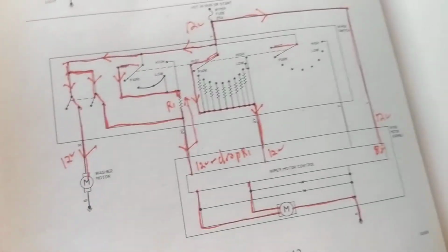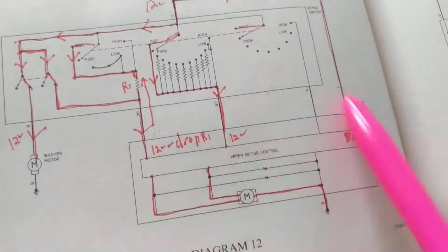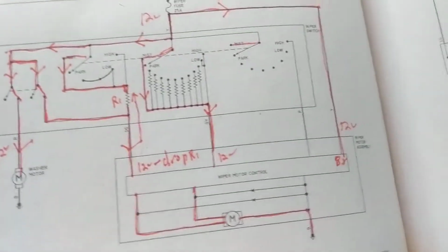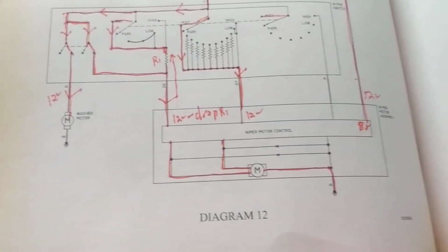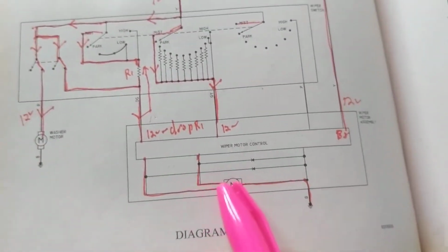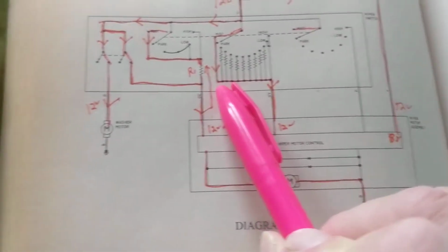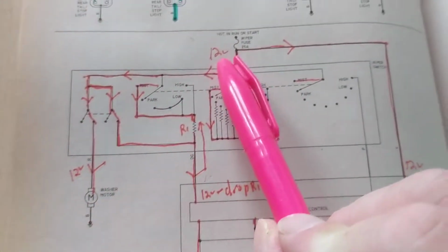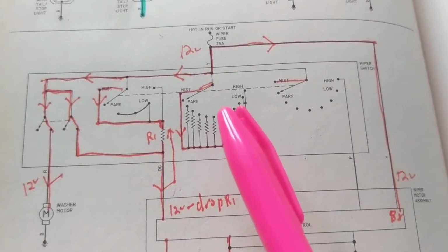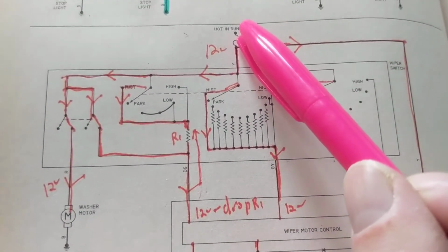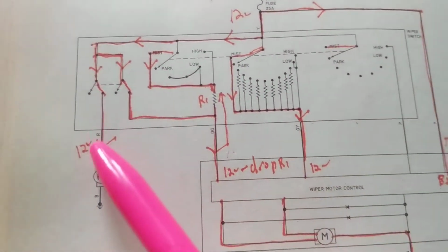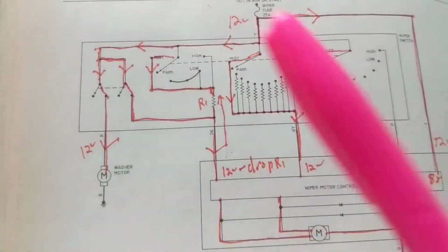Now, from troubleshooting, I'm going to start interpreting and analyzing the schematic from the component that I think is defective. That's the difference. When you're troubleshooting, if I think there's a problem with this motor, I'm going to start from this motor and work my way back. If I think there's a problem with the fuse, I check the fuse and it's blown, I'm going to go to that defective component and work forward to see what this is feeding. That's the difference.